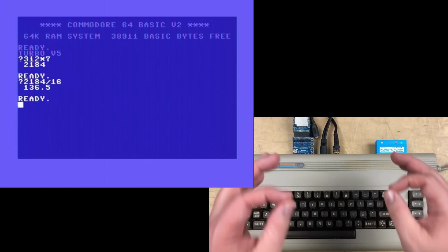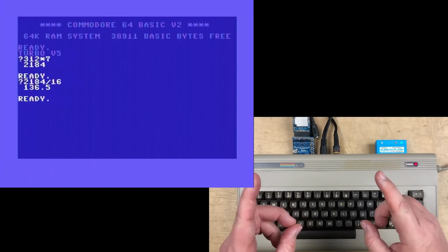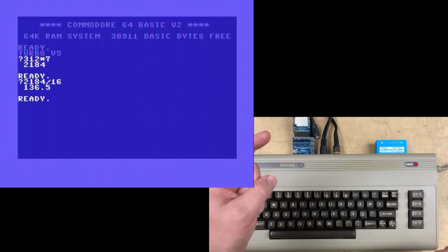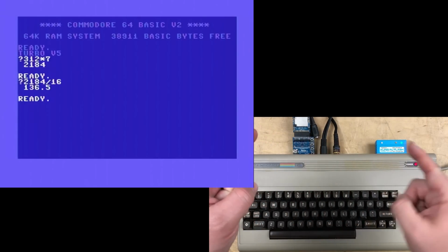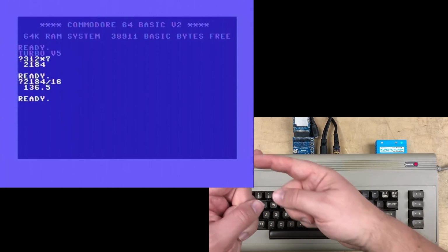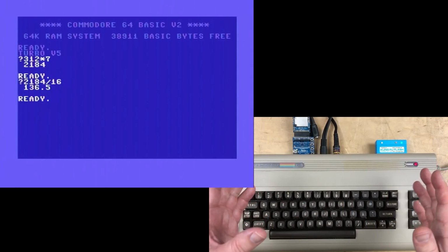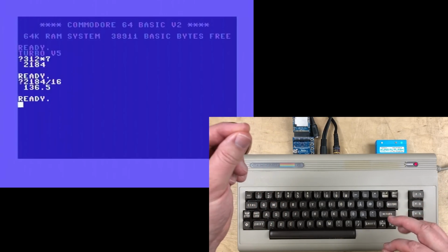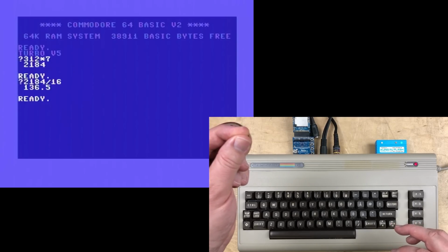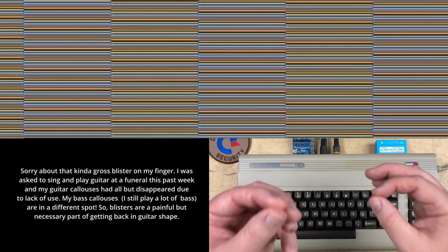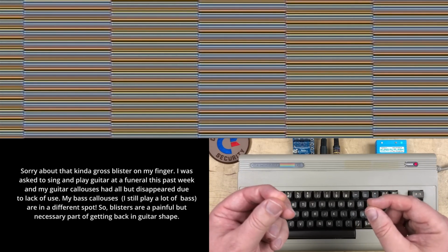It's science. I thought we were going to find that 16 went in with no remainder, so that over the course of a frame, if you happen to start with color 0 up in the top left corner, that because of the number of border color changes, by the time it got down to the bottom right corner, it would just flip back to 0 at exactly the right moment. That's why it looks stable. But instead, it seems that every second frame is going to flip back to 0. So it's going to be color 0 on one frame, then on the next, it's going to be color 8, and then on the next, it'll be back to 0 again. It's flickering the two at half time and creating a stable flicker color.